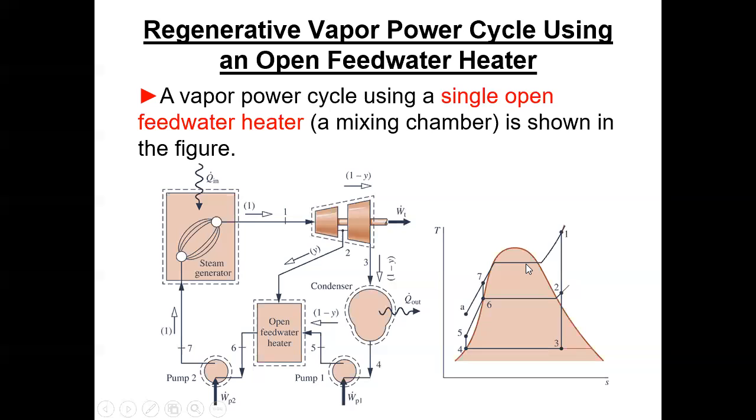And again, that's what gets compared and contrasted to the gas turbine cycle, which has a compressor. And when you start compressing, oh, it's a whole other ballgame. You're looking at 25, 30, 35, maybe 40% of the output of the turbine. Say the compressor and the gas turbine are put on the same shaft. So that poor turbine is driving a compressor on one side and a generator on the other side.